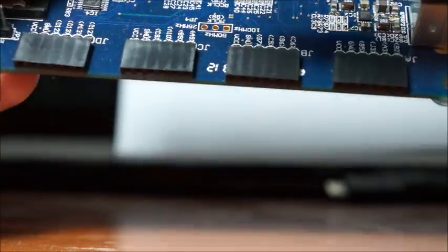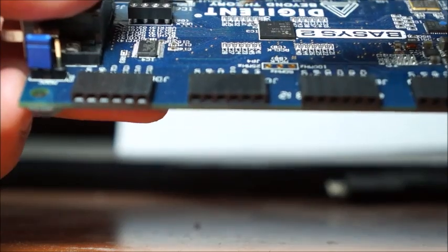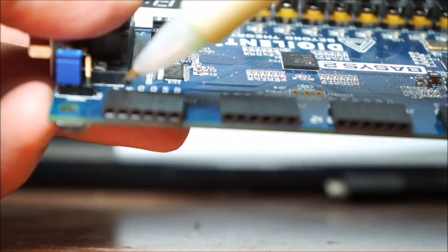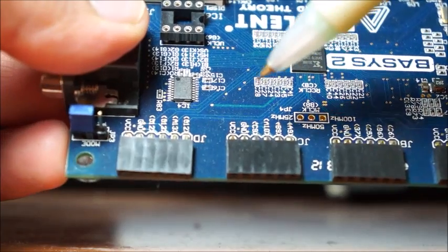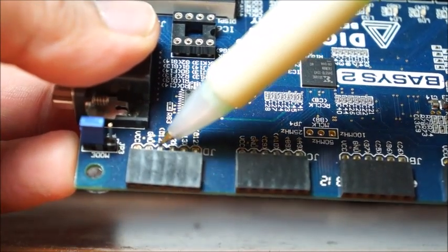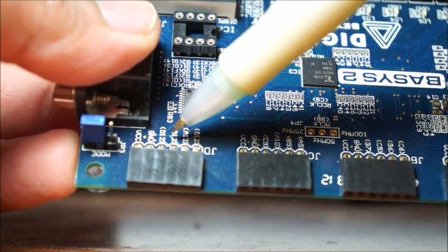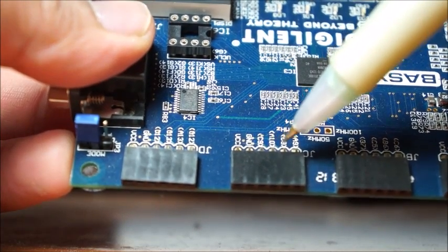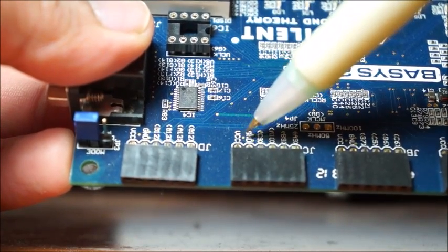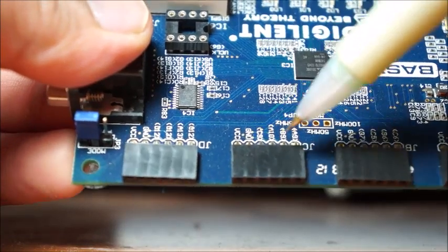Also make sure you know that this board runs off of a 3.3 volt supply. So all the voltages at these pins are 3.3 volts. So if you're trying to connect any other device that runs from a different voltage, you might need to connect a level shifting circuit to match the logic supply of the other external circuit.